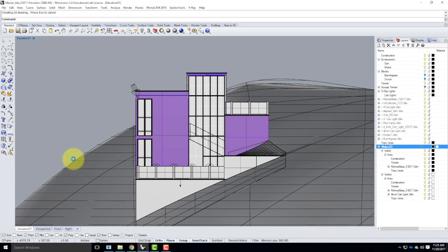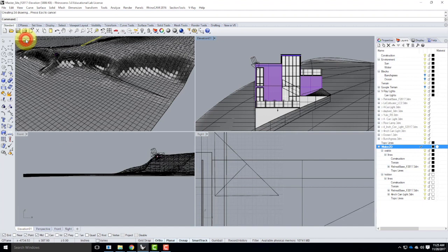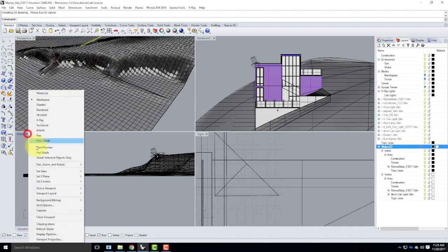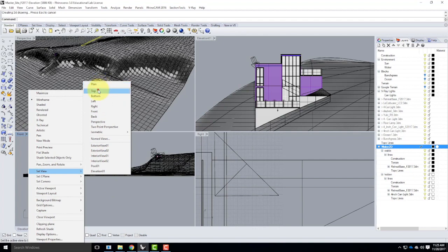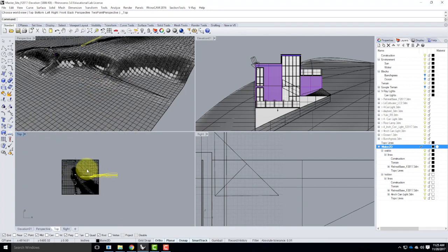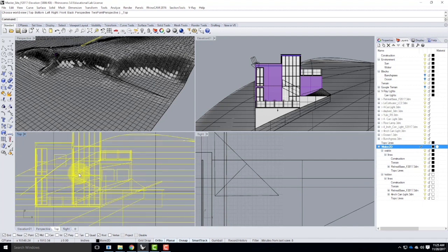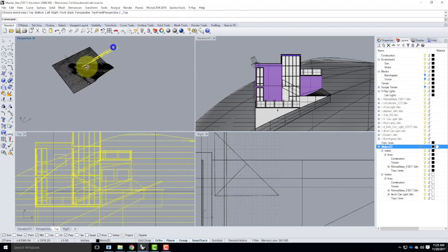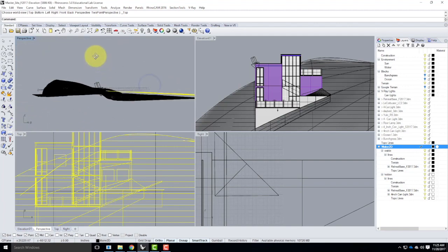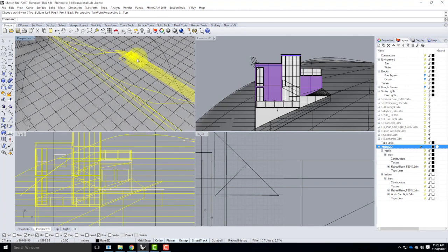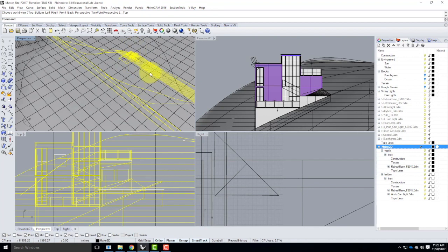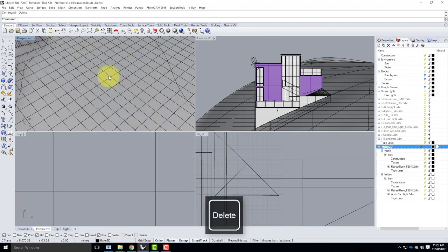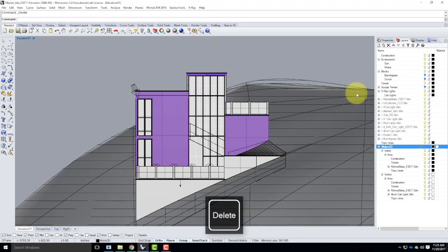All right, so it did that. And if I were to look at it in the top view, so let me go to Set View, Top. There is a flat line drawing of this elevation view. You can see it over here in perspective. So there's that flat drawing that includes the whole elevation. Now, unfortunately, I forgot one step, and this is my mistake, so I'm going to end up doing this over again. But before I do Make 2D, I need to know the exact outer bounds of this elevation view. And that'll help me down the road when I try to line stuff up.